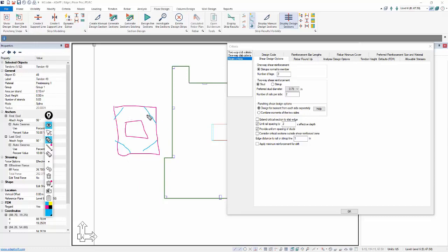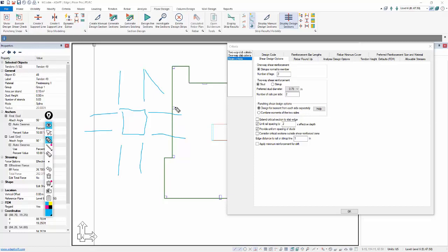If the stress exceeds 2 square root of f prime c for that critical section, then the program just continues to formulate those until we fall under 2 square root of f prime c. So this satisfies the requirement to check that octagonally shaped critical section. It's really a function of the reinforcement layout. It's really the least critical section, and our assumption here is that the rails project perpendicular from the column. So the least critical section is this shape.